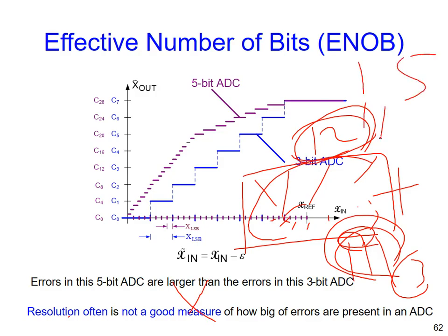You either have 12 bits, or in addition to 3 nonsense bits, you can claim, oh, totally I have 15 bits. But after buying the so-called 15-bit ADC, after measurement, he or she will say, wow, so bad. Not only 12, no, even much less than 12. It only gets 10 or even less, right? Oh, this is the huge difference. So don't believe in the name.